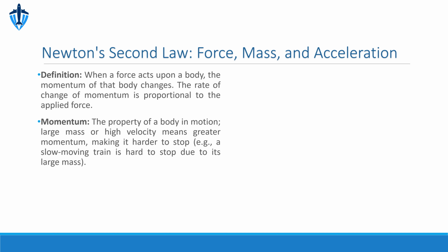To quantify mechanical advantage, we can utilize specific formulas. MA equals the output force divided by the input force, or the output distance divided by the input distance.